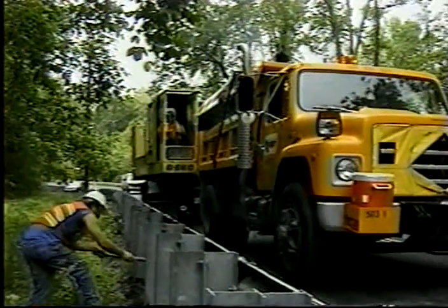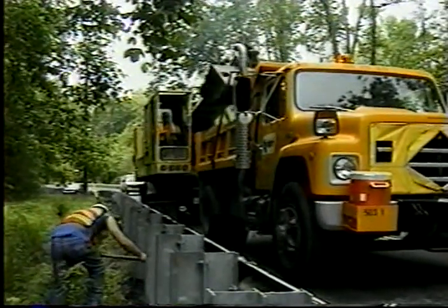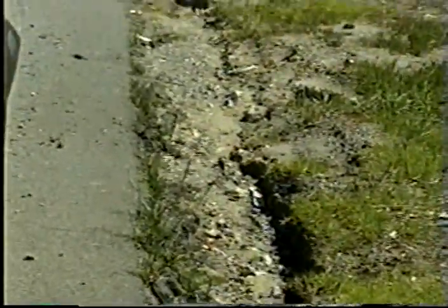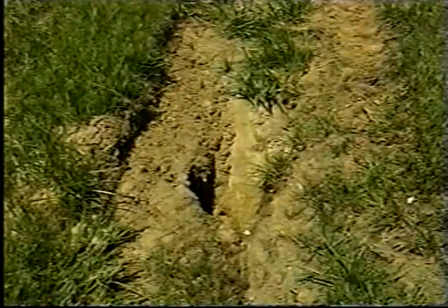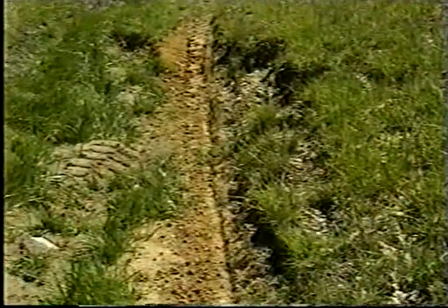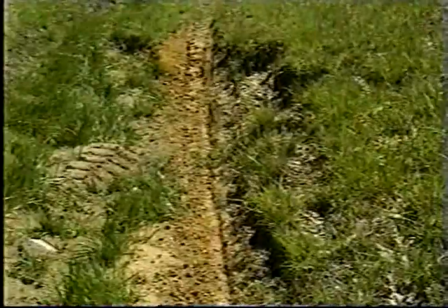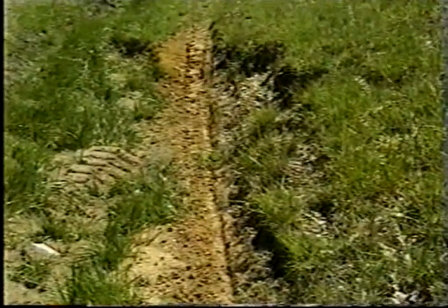Slope rounding can easily be introduced in normal slope dressing maintenance activities. Not only will erosion rutting be reduced by this operation, but also the safety aspects of the hinge point will be improved. Sodding or seeding and mulching will help reduce erosion. Erosion ruts on the front slope are particularly undesirable because vehicle wheels can be trapped in them, thus steering recovery back towards the travel lane is impaired.